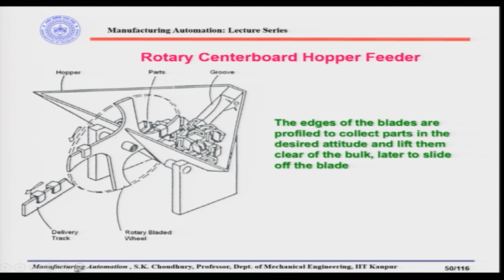So, this is also a very simple design, and as you can see, not all the time the number of parts will be the same. So, therefore, when you are finding out the average feed rate, you have to multiply by the efficiency, and again efficiency you can find out experimentally by rotating a few times and finding out how many parts on an average are coming per rotation.